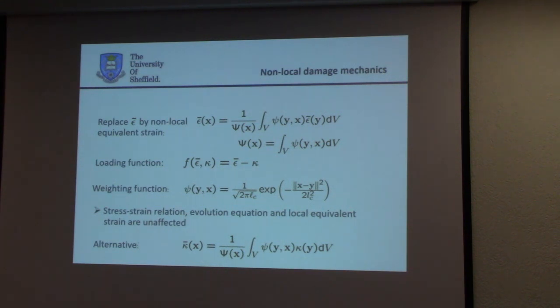Physically, that translates into that your crack band zone, the width of your crack band, for instance, if you have a number of microcracks, or your fracture process zone becomes larger. This L is directly related to the length of your fracture process zone when you are computing, for instance, quasi-brittle materials.